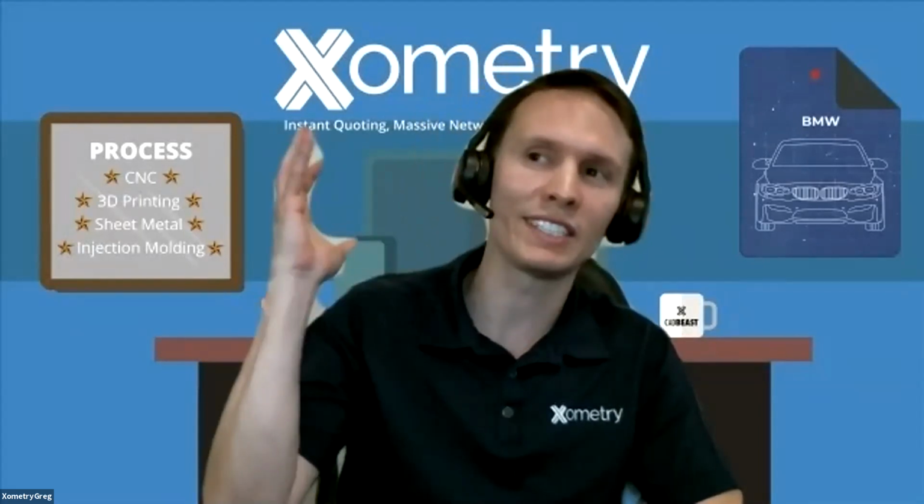I highly recommend SLA when you're looking for concept models, things that may be going to your CEO for marketing approval, or if you're doing a final fit check. SLA is one of the most true to CAD 3D printing processes out there. So if you're about to invest a lot of money in injection mold tooling, it could be worth doing an SLA prototype or two to verify.